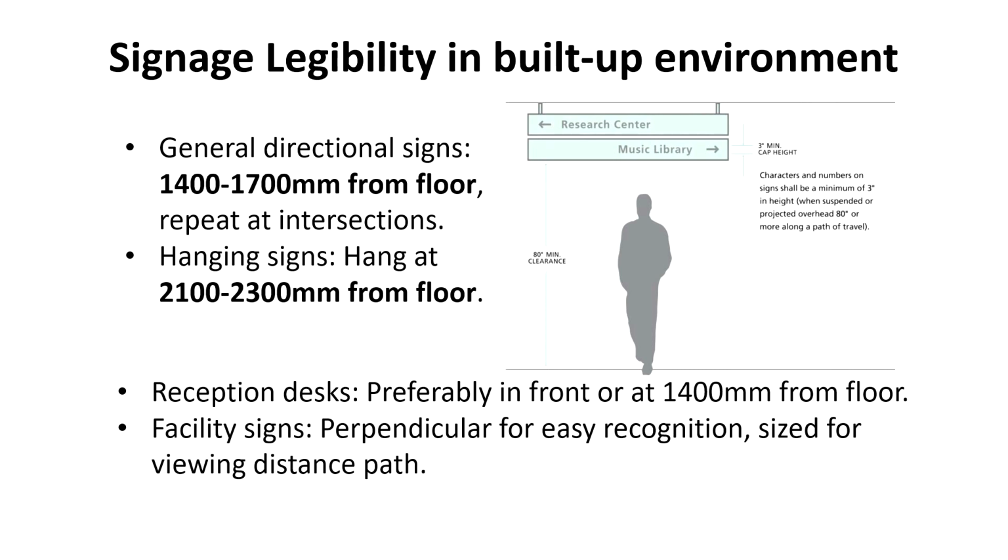What about the hanging signs? These are hanging signs that are placed at a right angle to the wall or hanging from the ceiling. The bottom of the sign should be 2100. That means it should not be less than 2100, which is actually also the height of a door. Or, for a larger crowded area, it can be 2300 or above, from the floor level.